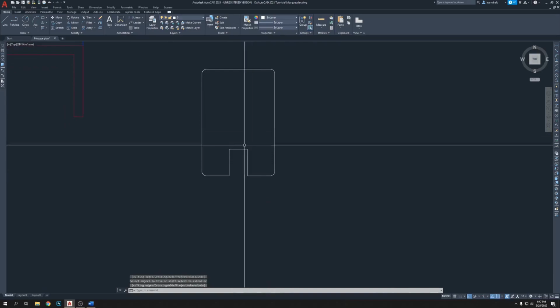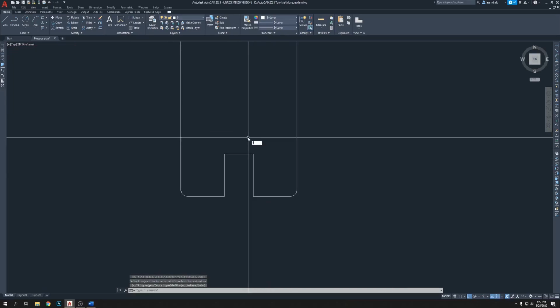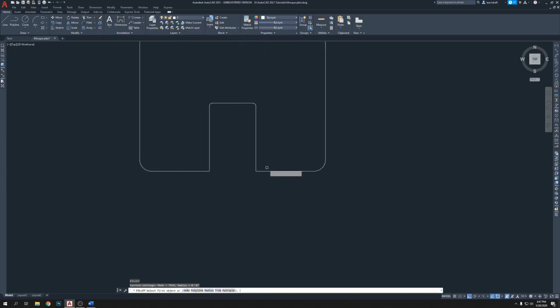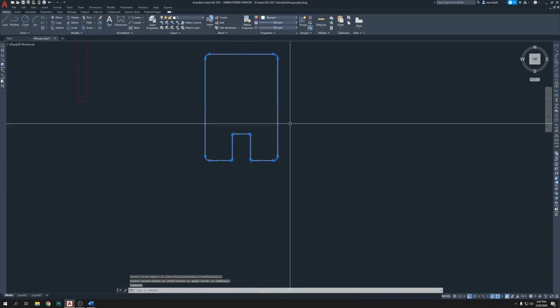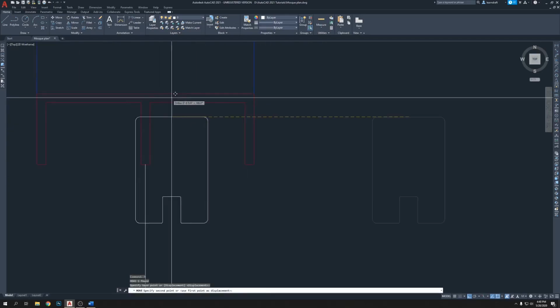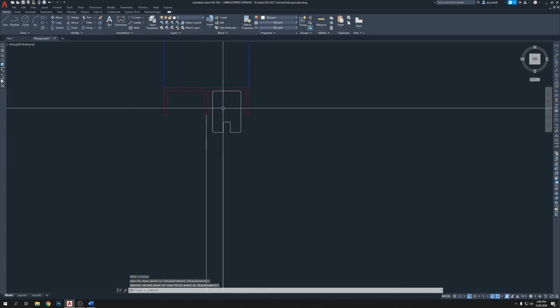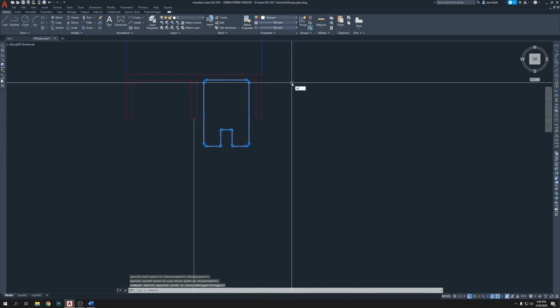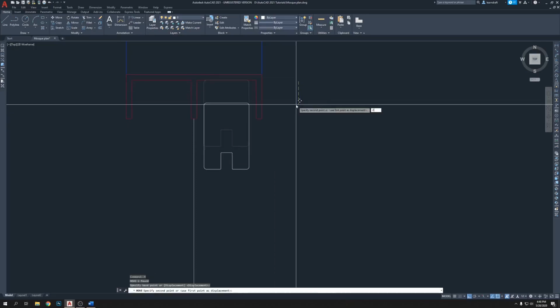and then going to fillet radius 0.03125, which is 1/16 inch, enter, click, yeah. So click this one, move it from here to there, and okay, bring it a little bit out, like 0.03125.